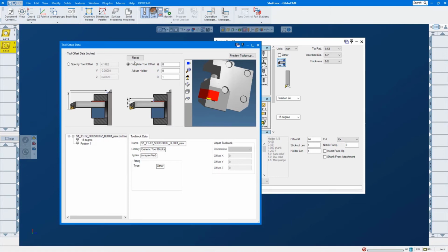And the way you can check that is by looking at this value right here, this Y value right here. And you can actually set this. Let's say you come in here and it's off by whatever amount, doesn't really matter. You can actually set it to 0 and it will move the tool into the right location and it will work. But that can tell you how far off you are. And basically you have to go back into the block and shift the coordinate system. Well, I would shift the coordinate system by the amount and then put it back in.